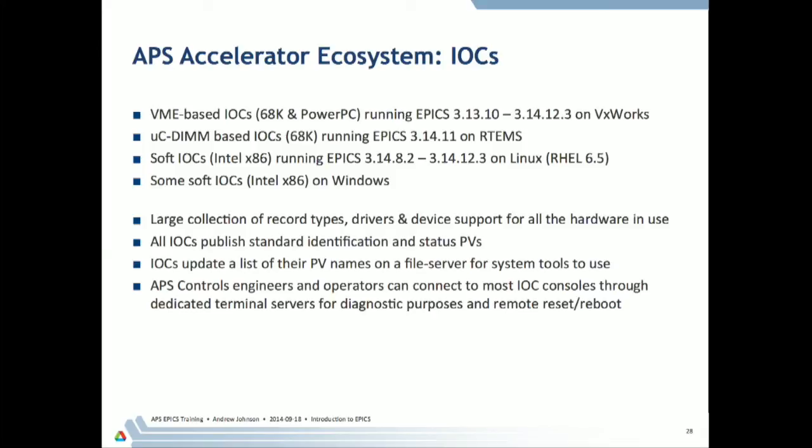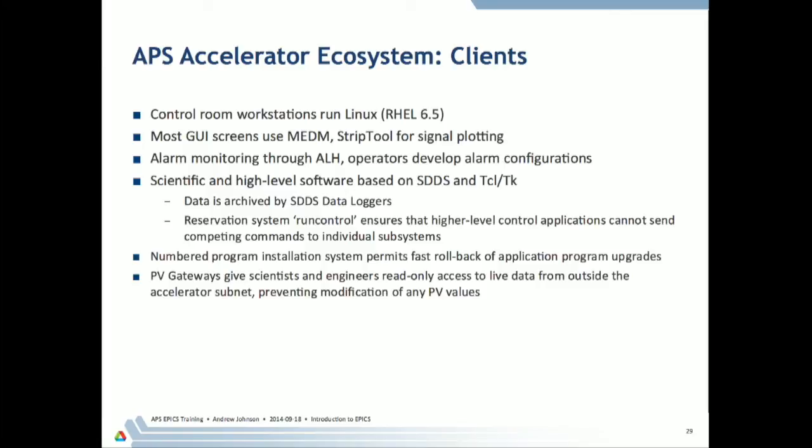And we also provide terminal servers connected to all our IOCs, so that the controls engineers and operators can log into the console and do diagnostics of any problems that they're seeing and see errors and so on, and remotely reset them. On the client side, the accelerator control room workstations are now all running Red Hat Linux, and most of our GUI screens are written in MEDM. I think we have one or two places where there are some EDM screens, because that's talking to a piece of equipment from a manufacturer that provided EDM screens for us.